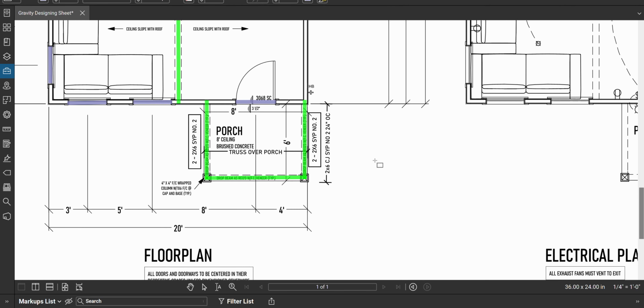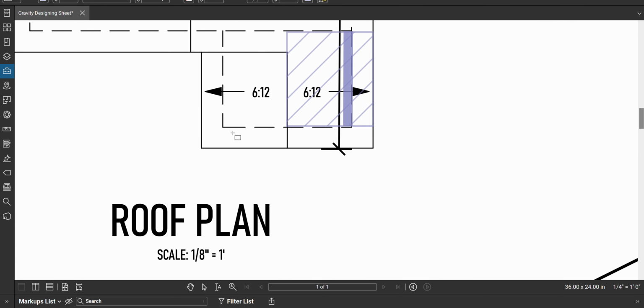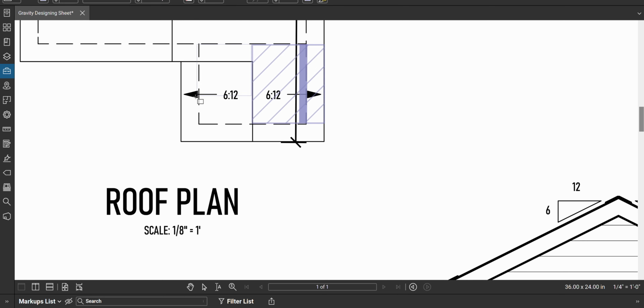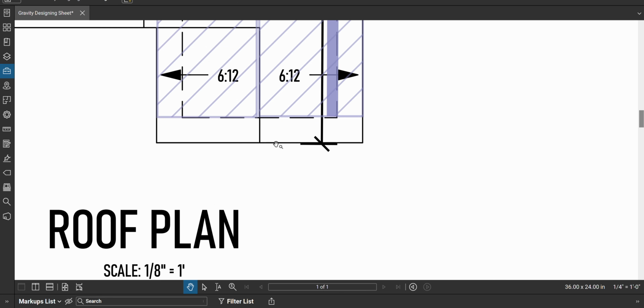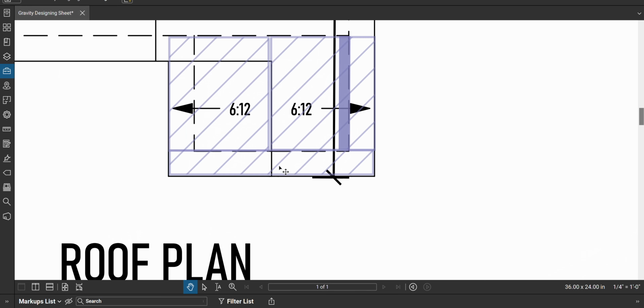What else might this be holding? Well, the roof. Yeah, there's an overhang here. There's an area here that's not being accounted for. One thing to think about, if you were to do these tributary areas for all the things you're designing, so I now have a left and a right beam done: if there's an area that has not been accounted for, you ought to think about what the heck is going to hold that thing up. Is it a wall? Is it something you don't need to calculate? That's fine. Just know that you need to think about what's holding that up if everything I've done hasn't accounted for it.